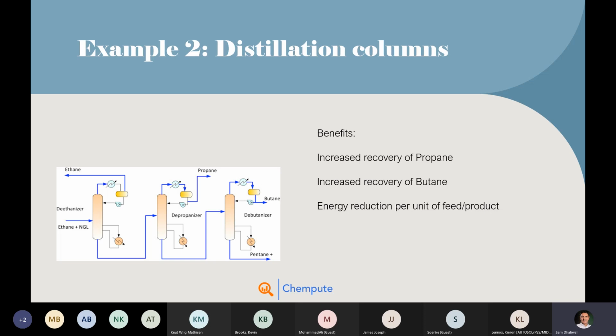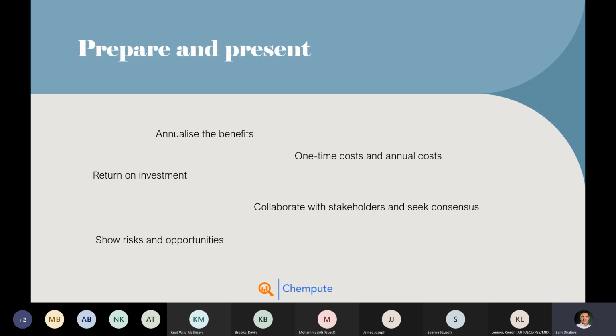Sometimes these reboilers are using waste energy from other processes, in which case perhaps you don't want to bother doing that calculation. But if they are directly using steam, then it's perhaps sometimes worthwhile doing that calculation. But from experience, energy is not a big contributor towards the overall benefits.